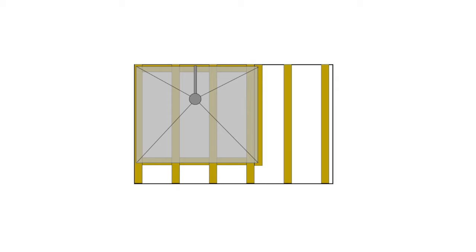It is sometimes easiest to build a supportive subfloor within the original joist space under the whole shower area. Using one of Aquatechnic's made-to-measure shower tray formers can save a lot of time, as the exact size and waste position can be manufactured to suit the individual wet room.